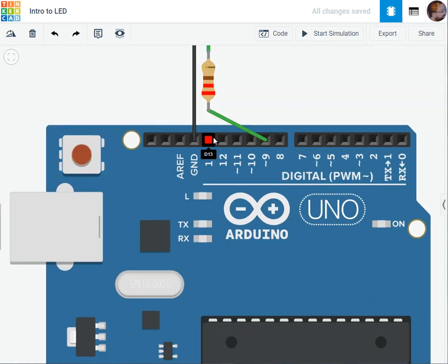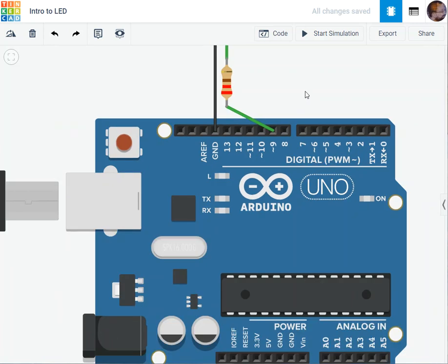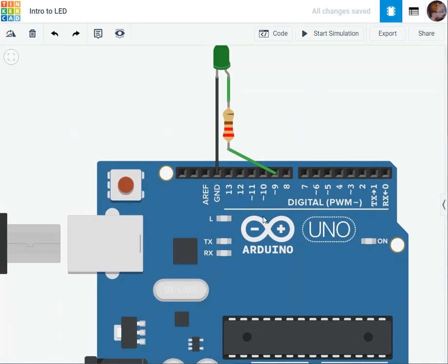So these here represent digital inputs. D stands for digital. It could be 0, could be 1, 0, 1, 0, 1. That's digital, so digital could be like Boolean. Boolean is only one digit, one state, either 0 or 1, while a bunch of zeros or ones would be binary. So binary could be 0, 1, 1, 1, 1, 0, 0, 0, 1, 1, 1. But Boolean would be 0 or 1. That's it: true, false, high, low. You have to keep this in mind. So when I say D, that means this is digital.